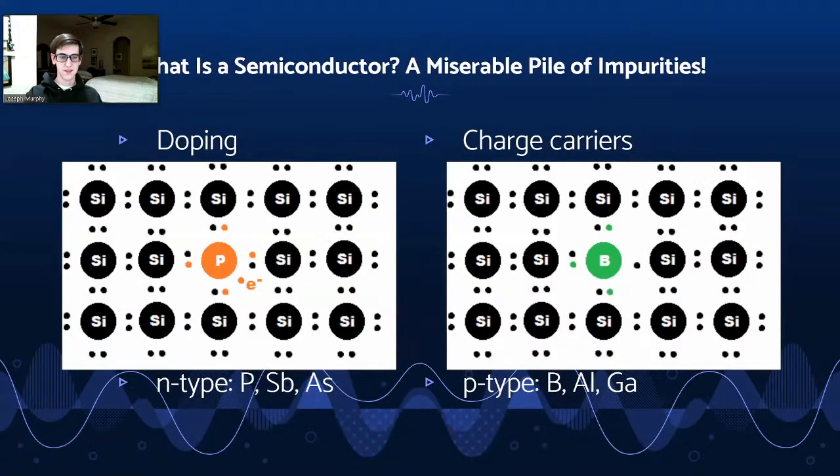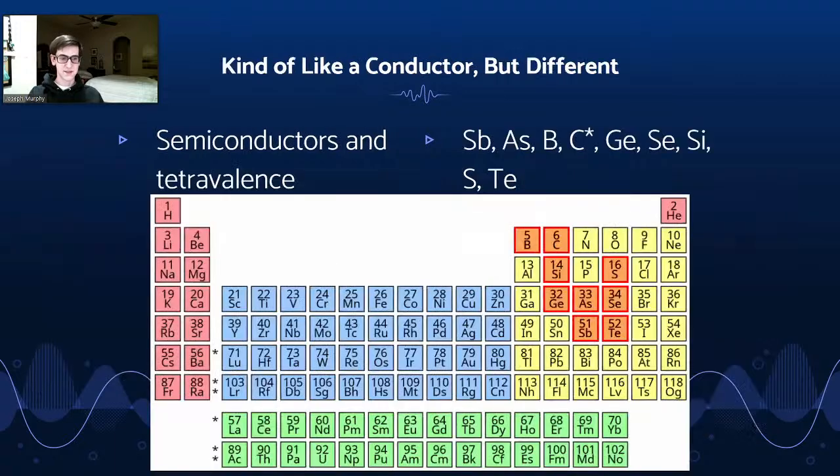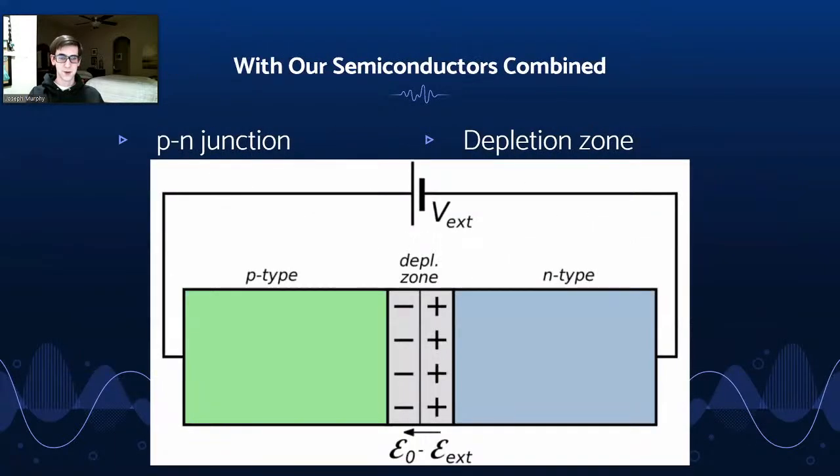If we go back to the conduction band diagram, remember that the Fermi level is the energy of an electron in the highest occupied energy shell at absolute zero. But we never work with absolute zero. We're always above that temperature. Especially in Texas, if you were a solar panel, I'd imagine your temperature would be quite above absolute zero. So some of the electrons in the n-type semiconductor will have enough energy to move from the valence shell to the conduction band and become mobile.